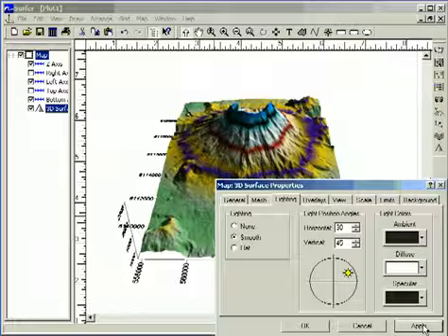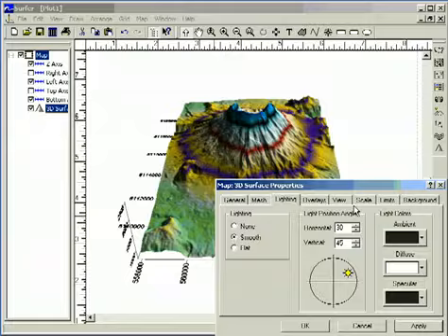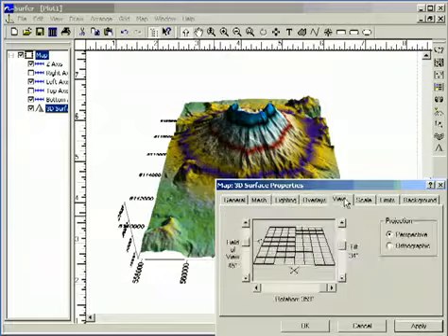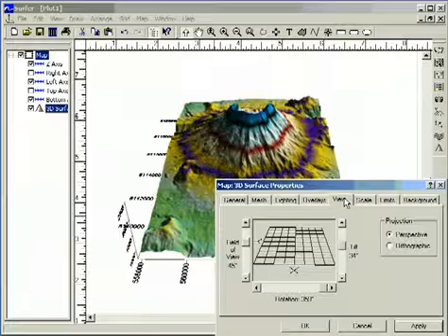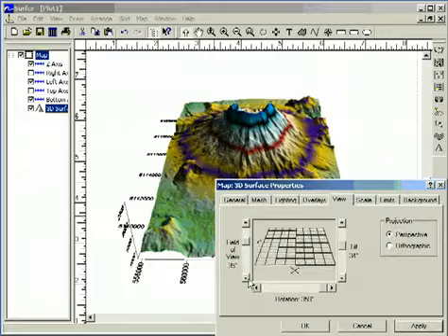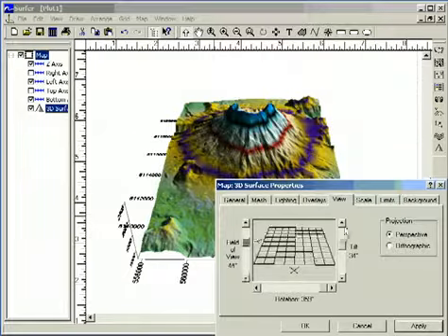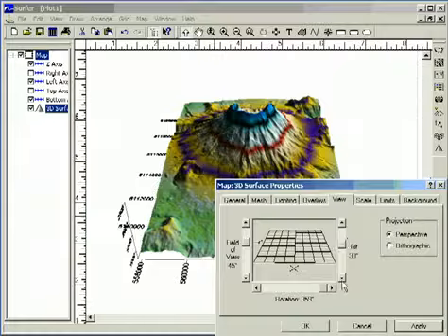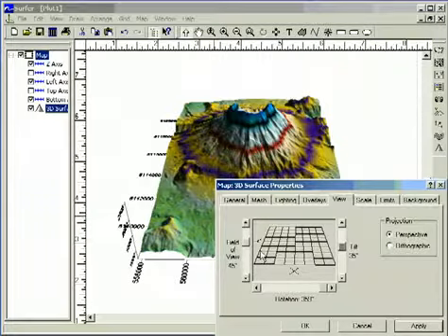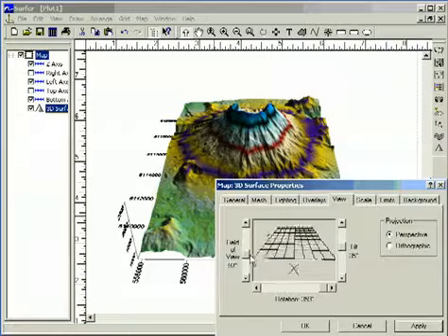The orientation of the surface can also be changed in the Properties window by selecting the View tab and adjusting the tilt, rotation, and the field of view. To do this, select the up or the down arrows located on Field of View or Tilt, or click on the box in the slider bar and drag it to the location you wish.